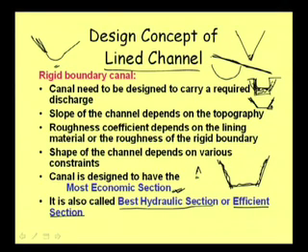And our objective will always be to carry the maximum discharge, or the required discharge, at minimum perimeter, provided the area remains the same. If we talk about excavation, excavation will depend on the sectional area. The volume of excavation will be the sectional area multiplied by the length. If we cut the channel with that length and this area, then excavation comes up. Now, if this area remains fixed, then this excavation A into L, that volume, will remain the same, and as such the cost of excavation will remain the same.